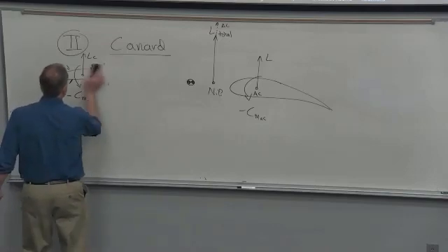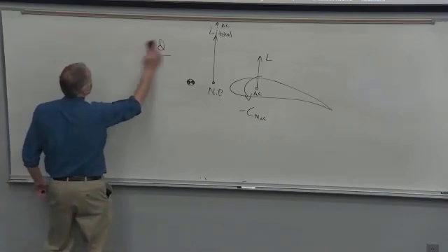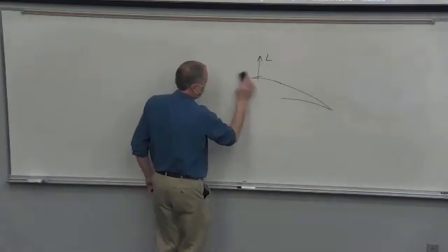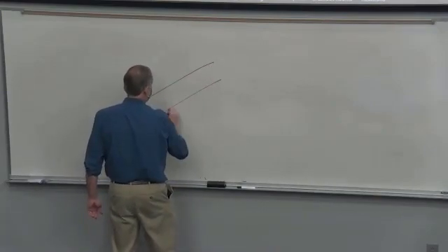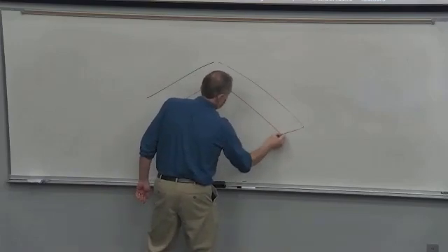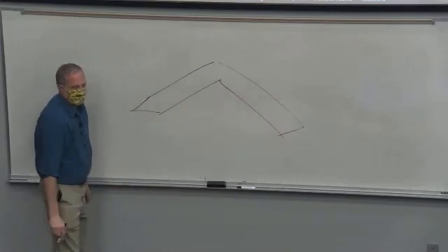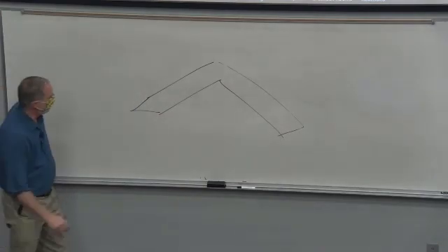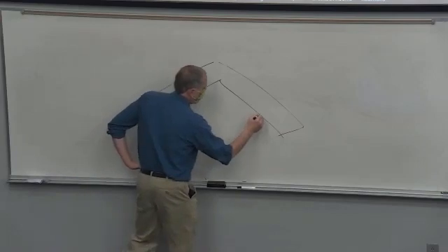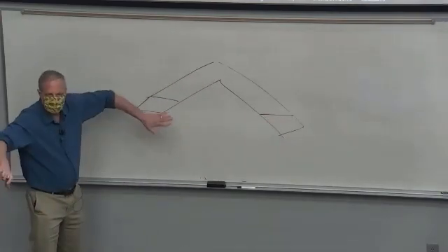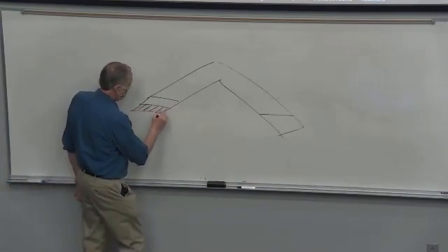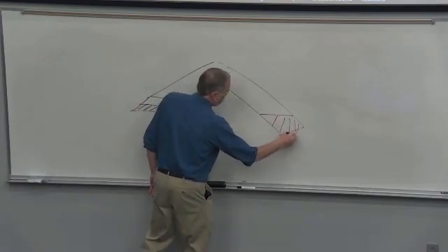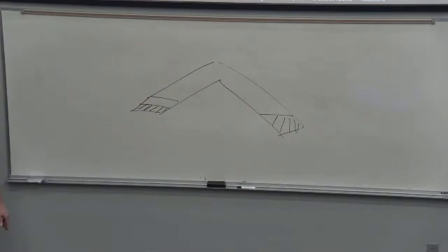The other way you can do a flying wing is you can sweep it back. So if you have a flying wing like this, we said, well, we need a tail, right? Well, because the tips of the wings are swept back, you can take the tips of the wings and you can twist them to give you the pitching moment to balance out. Or you can put control surfaces, essentially an elevator. I've kind of drawn a weird wing here. But you can adjust those, like the elevator on the tail, to get the pitching up or pitching down that you need. Yeah.